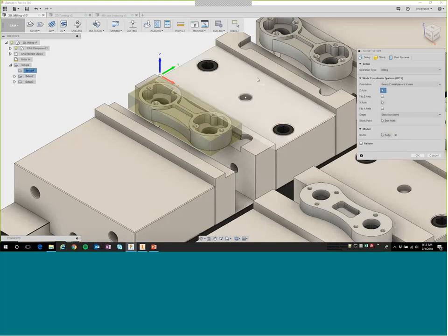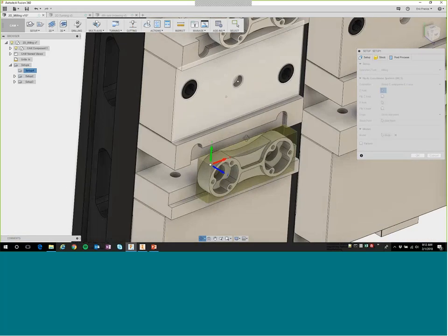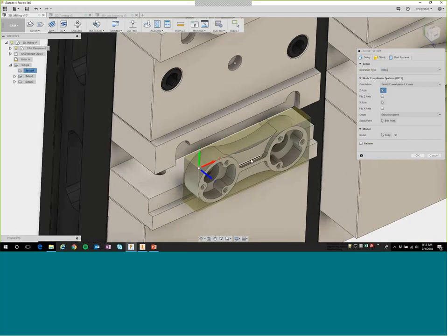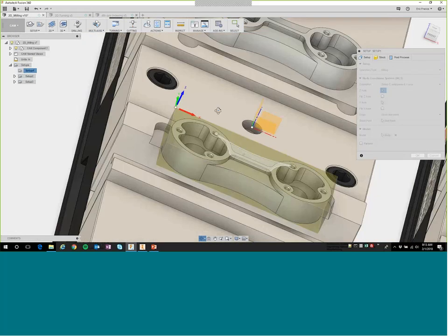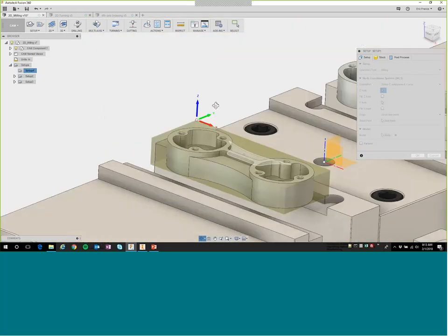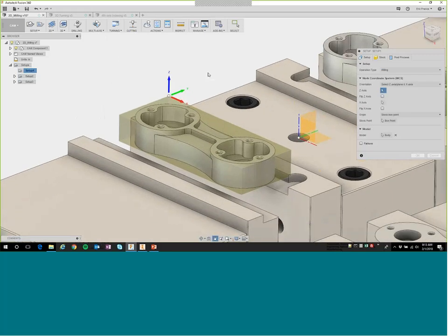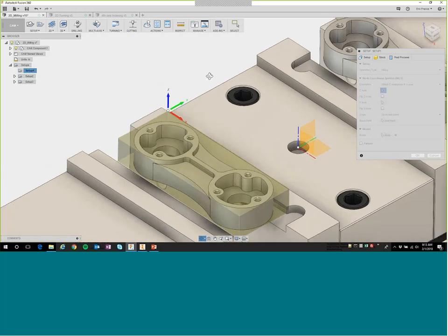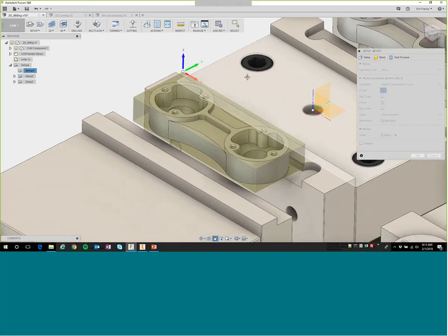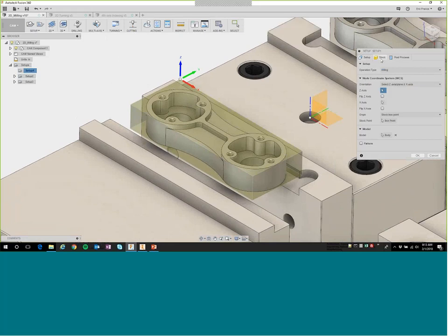Another nice option is if I happen to be doing some tombstone machining and actually need to reorient my Z-axis, I have the ability to go in and just pick a face I want to be normal to, and it'll go in and adjust those automatically, right? And if I don't need to do that or need to flip that around, it's just a matter of making a different selection again to get back to that stock box point. So some nice functionality just with setting up our work coordinate system and identifying where that origin needs to be.